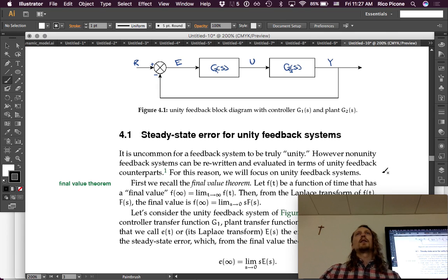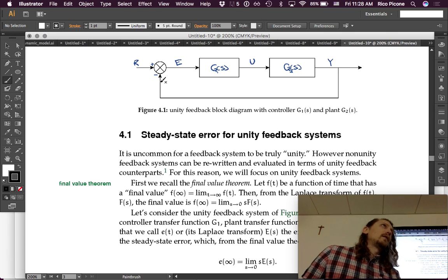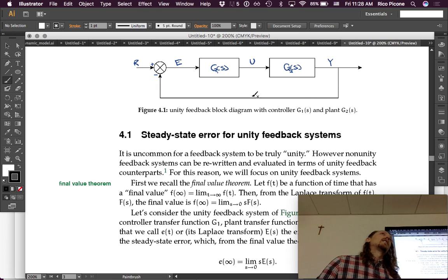You can also derive what we're going to do here with a non-unity feedback situation too. It's just a little easier to think about with unity feedback. Unity feedback means that whatever the output position is, you know exactly what that is without it going through any dynamic element. So when you make a measurement of it, sometimes there's a dynamic element in your feedback path, your instrument, that has an impact on the dynamic response a little bit.